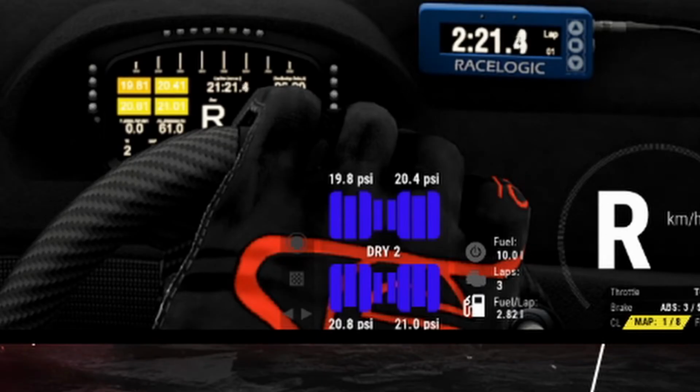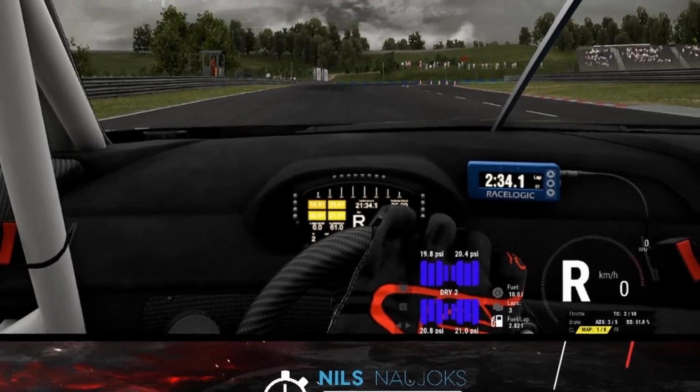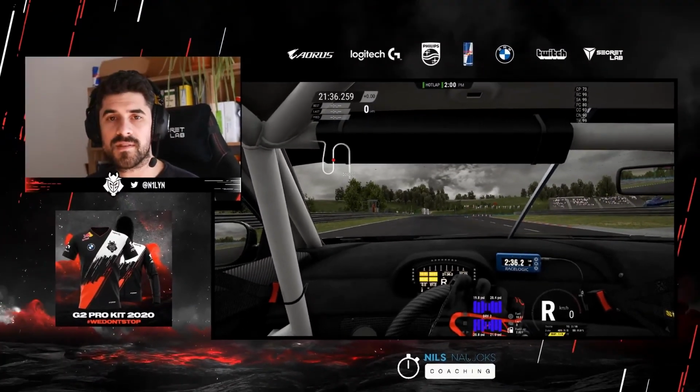If the middle pillar is too small, then it means that the tire is underinflated. If the middle pillar goes above the other two on the outside and inside of the tire, it's overinflated. So basically you just want to look out for this pillar being the same size as the inside and outside, and that usually will be reached somewhere between 27.5 to 28 psi.